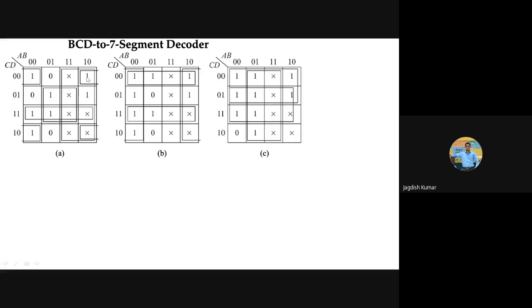These don't cares are really helpful in simplifying K-maps. When you are solving for sum of products, we will consider all those don't cares or X's as ones. If you are solving product of sums, then you will consider all of them to be 0. Don't care means there is no problem; you can take them as anything. Output has nothing to do with those input options. So to simplify K-maps, we take all of them as 1. That will help us simplify the K-map.